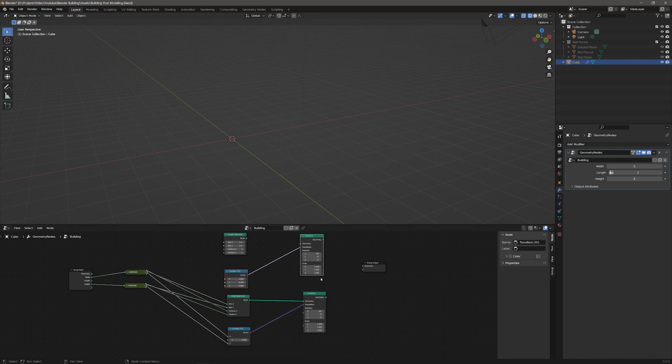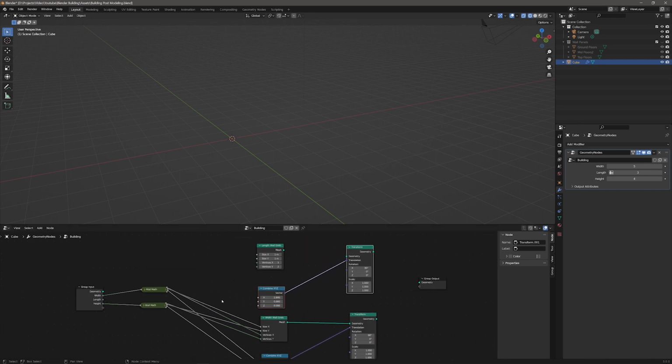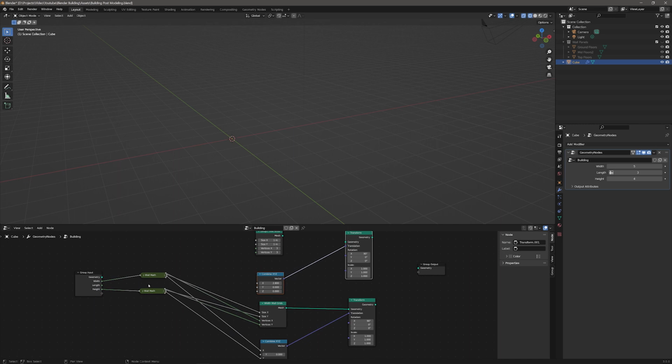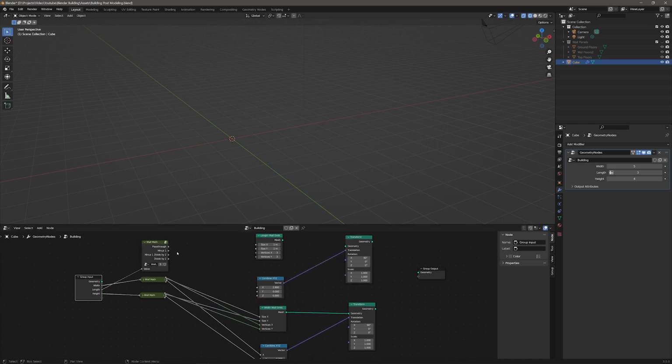and I'll copy the structure that I use to transform, but instead of using the width and height, I'm going to use the length and height. So I'm going to make a duplicate of my wall math, open it up, bring length into it. The same spots where I use the width values, I'm going to use the length values. So length -1 now goes to size x, pass-through goes on vertices x, -1 divided by 2 goes on transform x,